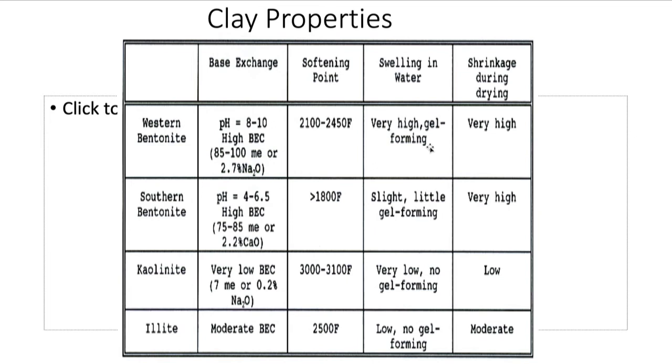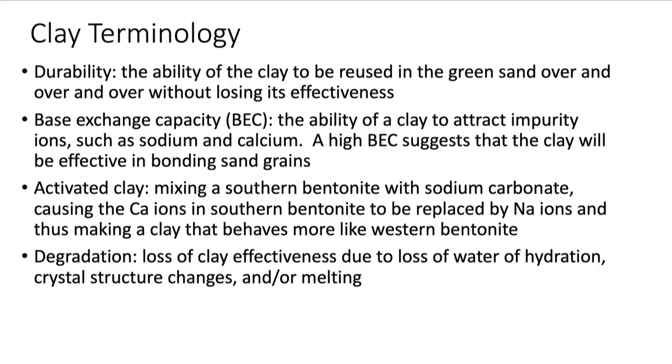That means that it swells up in water. In fact, they'll typically put Western bentonite in a pond if you don't want the water to go through the earth. They also use it in the bottom of, what do you call it, like a dump, where if you're trying to contain chemicals, they'll line the bottom with clay in order to keep those chemicals from contaminating the area around it.